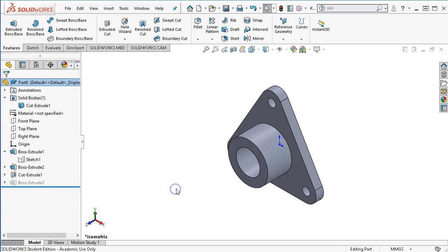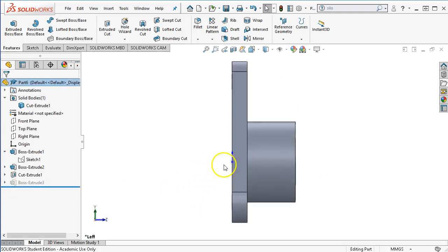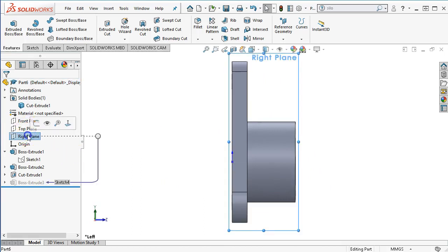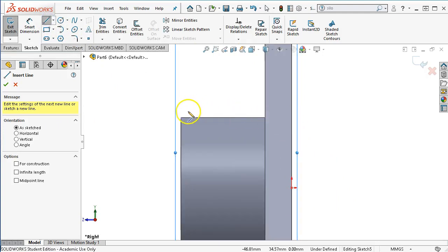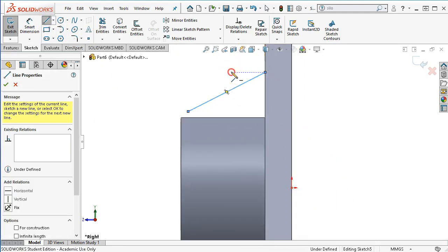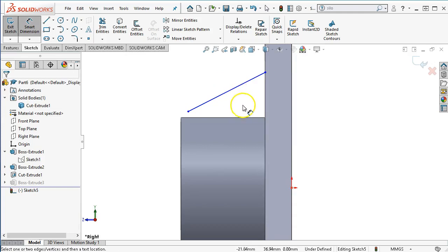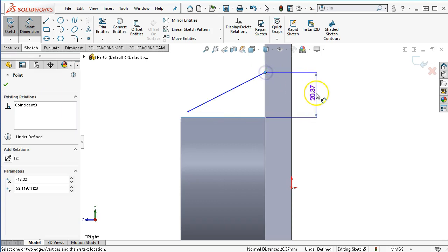So whichever of those will work. All right, right plane and sketch. For the rib command, I just need to create the geometry. There's the silhouette edge. It finally came up, so I'm not sure what was going on. But that little cylinder with a line through it is telling me that I can pick an imaginary edge where the plane passes through that cylinder, and there will be two solutions for it.